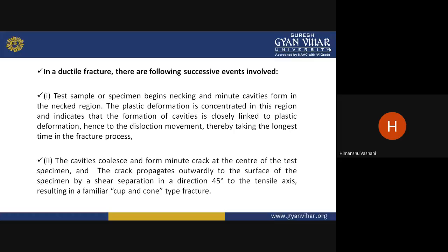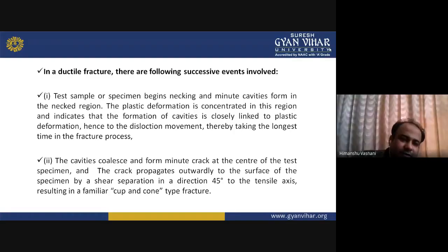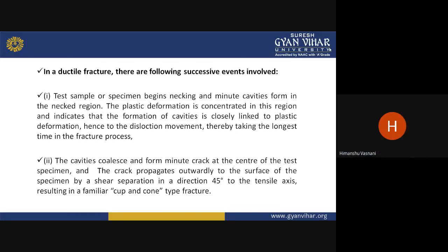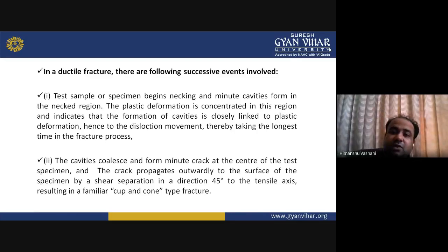The test specimen begins necking and minute cavities form in the neck region. The plastic deformation is concentrated in this region, which indicates that the formation of cavities is closely linked to plastic deformation, hence to the dislocation movement, thereby taking the longest time in the fracture.